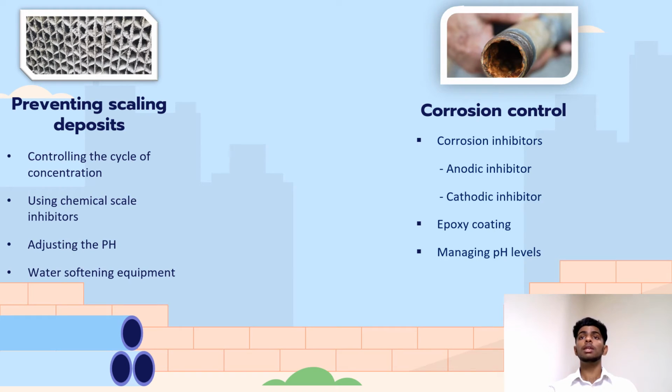And then the second is epoxy coating. Epoxy coating helps prevent corrosion in certain circumstances. Coating the metal with thin films prevents free oxygen and water from coming into close contact with the metal surface. This breaks the reaction cell and reduces the corrosion rates.